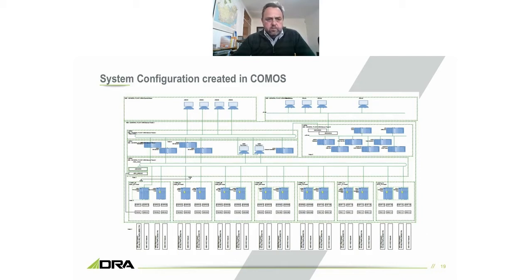We're seeing COMOS being structured to allow close integration from instrumentation design into control systems design, which we like, especially as a lot of our designs, let's say if you're using EZBus, for example, the integration between control and instrumentation is very tight. We can pull out the network drawings that we want done in COMOS, link that through to our PLCs. We haven't closed that loop yet, but we certainly know that it's possible. But this network design was done in COMOS, and we would construct off documentation like this.